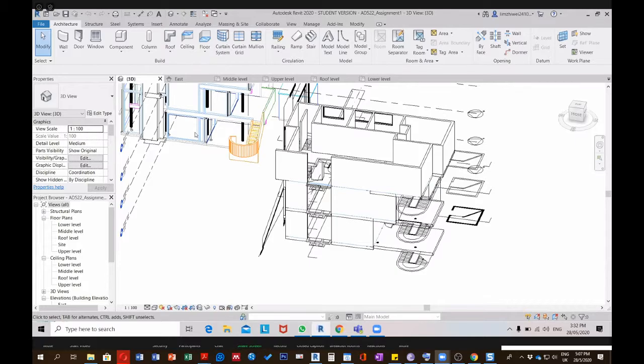There is another technique actually. Okay, let me delete this one. When I select wall, you see there is this one. It's like there's pick line. So it means if I pick this line, automatically a wall will follow this line. If I select, for example, this line, even though it's not correct, this one is glazing. Let's say this one, for example. See, there is a wall automatically. We'll make it shaded so you can see this wall.